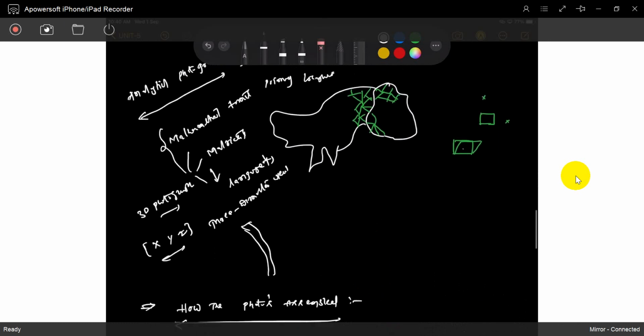This is the theory reference to how we took the photograph. We already discussed how to interpret the photographs, the scale, the error. But this is the before part and the after part. Before, we have to select some ground control points, and later, based on the ground control points, we assemble the photographs like this.